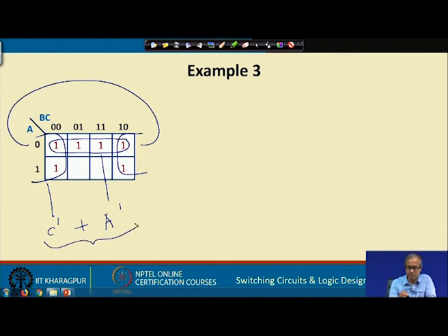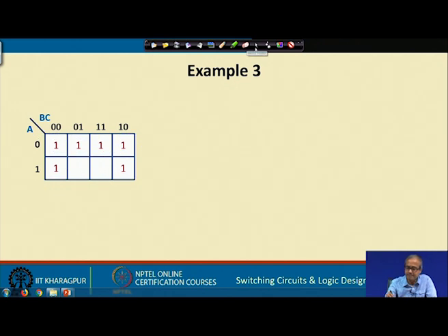right. So, you should notice or note that when you create these cubes, your cubes should be as large as possible, you try to make them as big as possible, then only you will get the minimized form. But you see the advantage, I do not have to go through any algebraic technique, just pictorially you form the cubes and directly write down the product terms from there. Okay. Let us take some more examples.